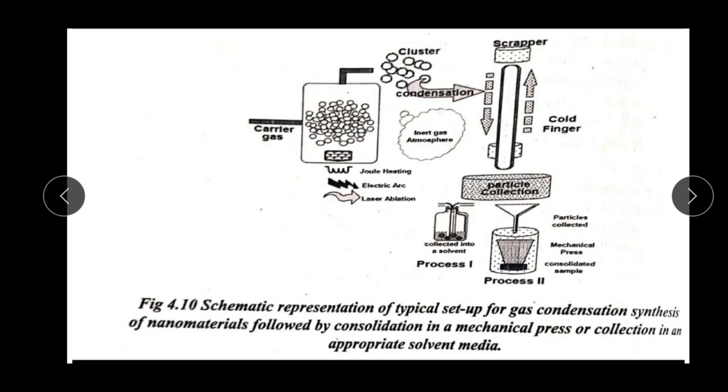In addition to this cold finger device, several techniques known from aerosol science have now been implemented for use in a gas condensation system, such as the corona discharge etc. These methods allow for the continuous operation of the collection device and are better suited for the large scale synthesis of nanopowders.